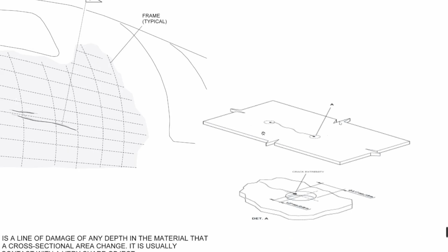It's done by a sharp object, so usually with your fingers you can feel the sharp edge of this scratch. And because the scratch is very thin, it's very difficult to evaluate how deep it is. That's why we are blending out. Blending out is removal of all these edges. We are making the area smooth. So finally, we can investigate this scratch like a dent.